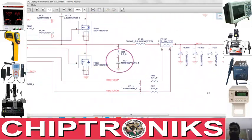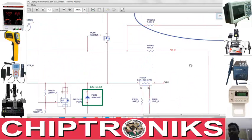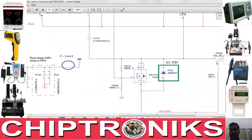Now this ACOK will also make this MOSFET conduct. If this ACOK is coming over here, this is conducting, so the ground will shift over here, right? The ground will shift over here, so the current will flow across this transistor. It will become active, and the current will flow across this resistance. So the voltage across would be approximately 6 volt. This is a P channel MOSFET. For a P channel MOSFET to operate, we know VGS has to be negative. Here voltage at source is 19 volt, voltage at gate is 6 volt, so VGS is negative, so it will turn on and it will generate Vin.